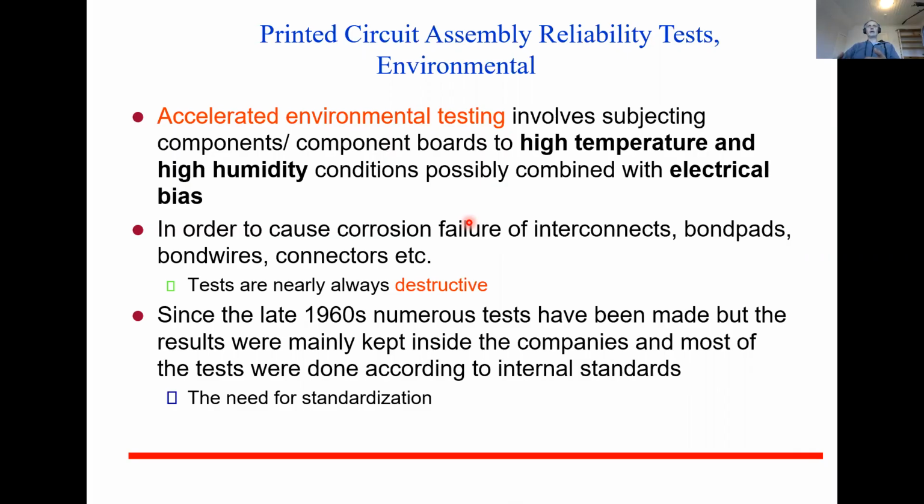As we saw, it might not be a recoverable change, it could be a permanent change. So you are cutting off a significant amount of lifetime, or you are decreasing the mechanical strength of the product permanently with that exposure. So that's the reason that hot and humid conditions are typically excluded from the screen. I think this is good to keep in mind.